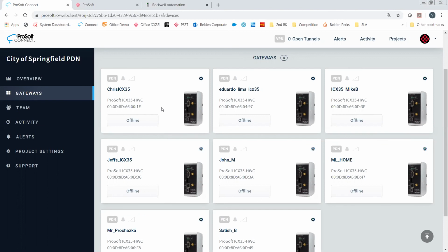To give you an idea what 3 gig buys you, let's take a water network, for example. I've got a customer that's got about 15 sites on this. They poll these sites every 9 seconds, and they are exchanging 100 words. Sorry, the protocol is Ethernet IP, so they read 100 words and they write 100 words. That particular system uses, on average per site, less than 2 gigabytes of data.